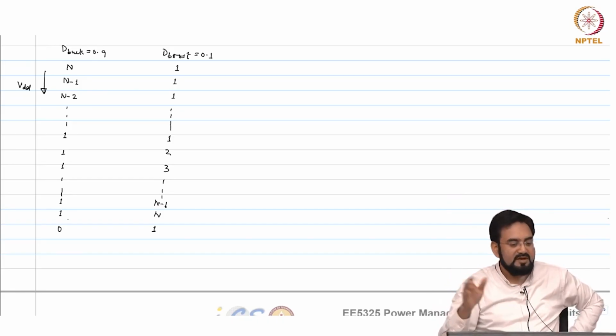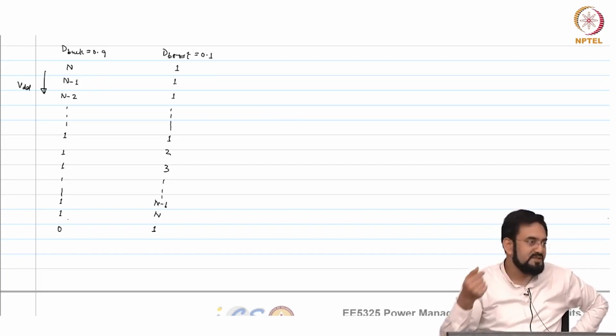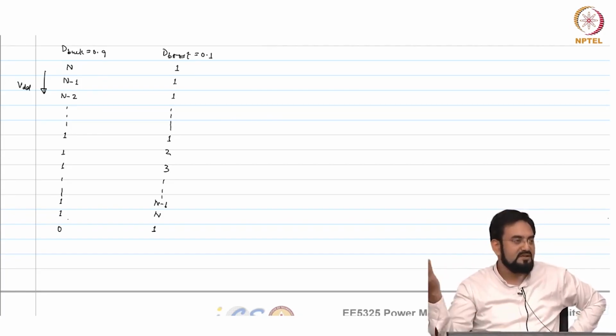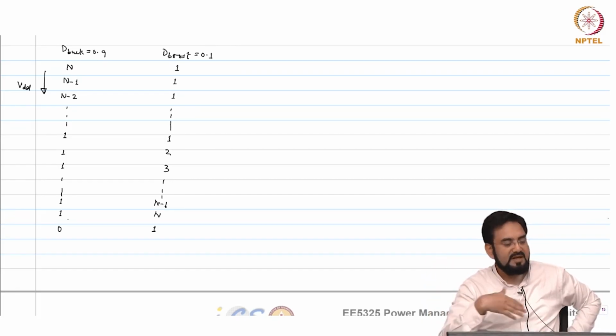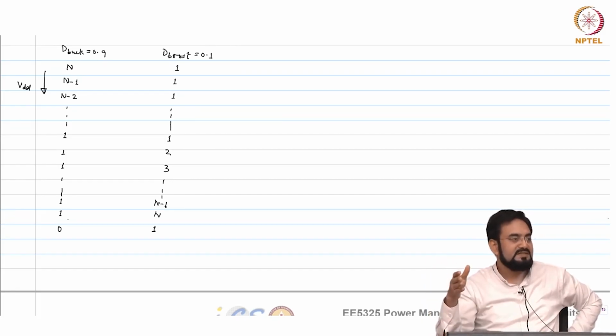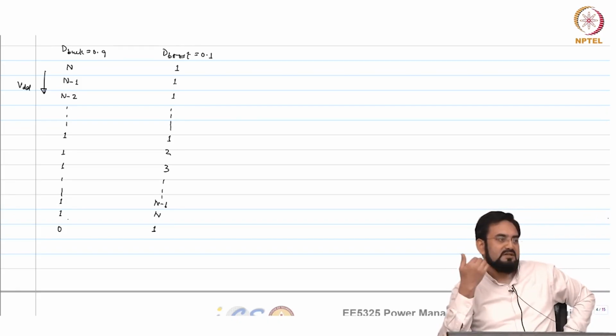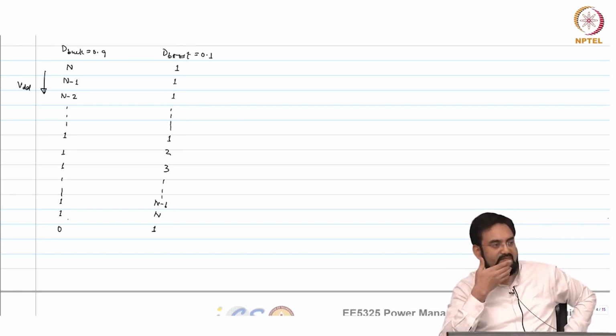So you do not need to always limit at 90%. It could be in some cases 95%, it may be 94, 92%. It all depends, so you have to run across PVT and see exactly where your circuit is not responding, what is the maximum duty cycle at which your circuit does not respond, and you just limit your duty cycle on that. From that maximum we can directly jump to 100%.